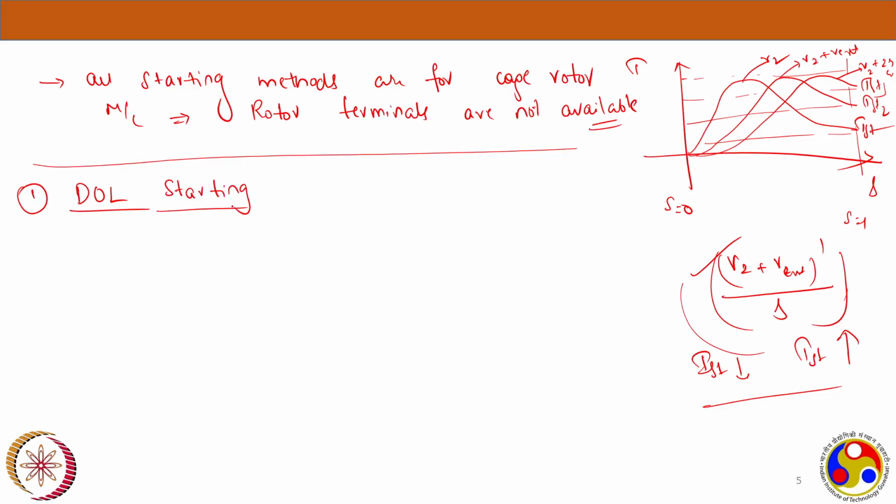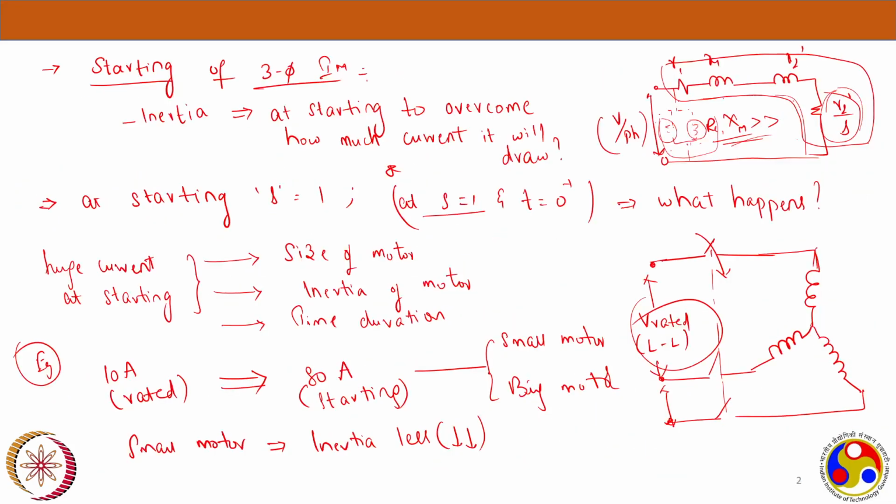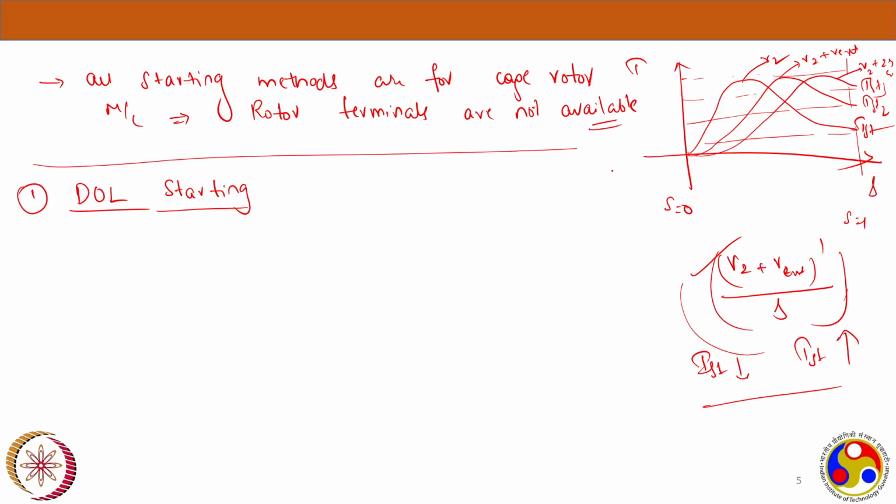Now see, we are always drawing the stator as a star, right? Even in the previous diagrams where I gave the supply, the stator is a star here, and again a star here. It's not mandatory that all stators will be in star only. The stator could be in delta also, like this kind of delta connected stator. But the reason we go for star is it's simple to represent, with simple connections and all. But usually the stator can be delta as well.